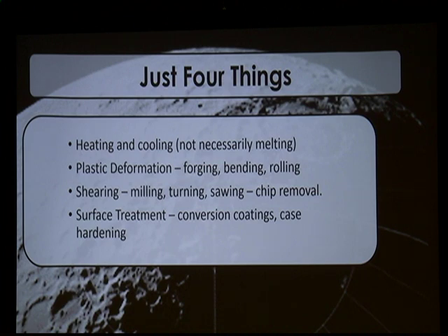The Japanese were fantastic with this. You've got 2 different kinds of steel, and it's differentially heat treated, so you've got a really, really flexible spine with a ridiculously hard, sharp edge, and it's sort of like the ultimate cutting tool without ever melting the steel. They just forge welded multiple chunks together until they finally got a refined product. We're going to be melting, so it's a lot easier.